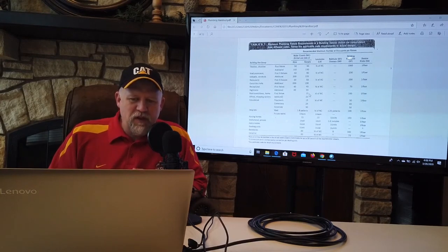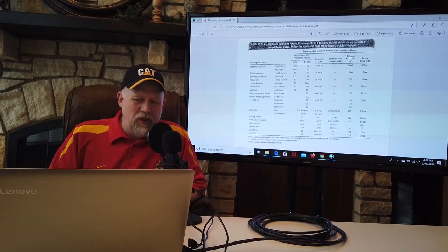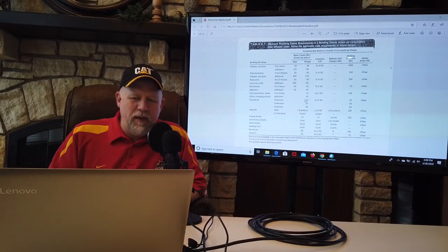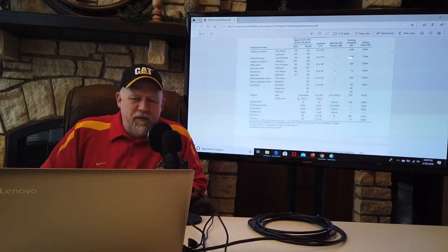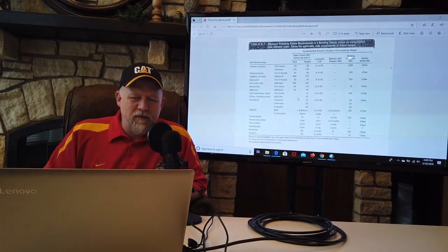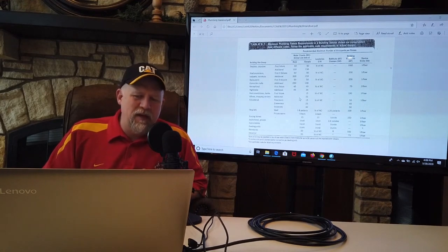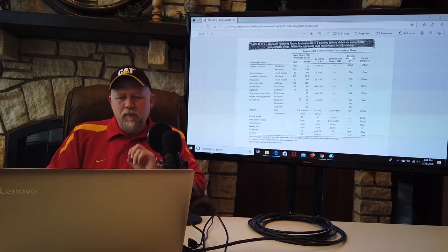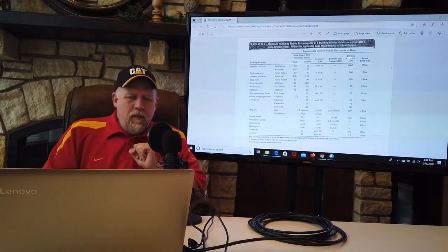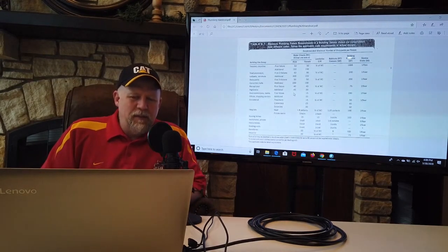The first fixture is for 15, and I don't know why they stopped printing both of these, but it should be the same ratio, men and women. So the first fixture covers the first 15 people, and then every 25 people after that, you need another water closet.